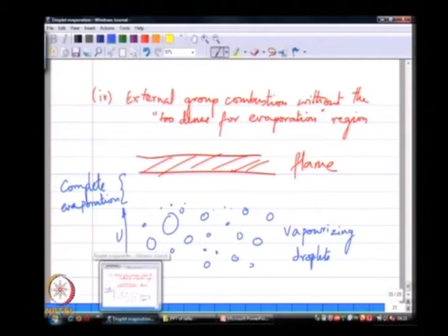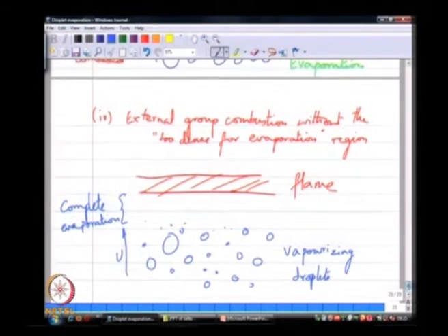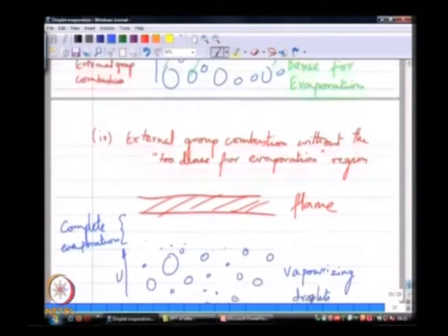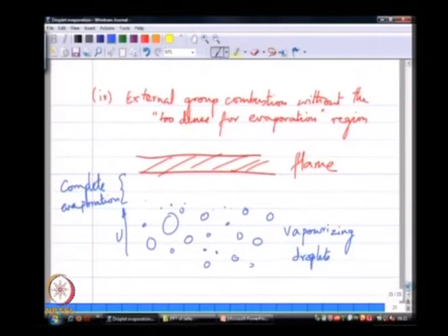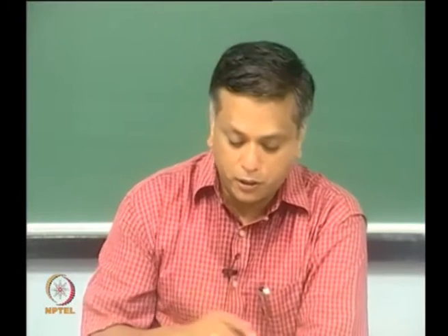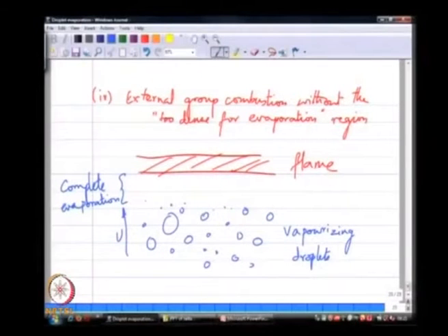This is our fourth mode of combustion. This is also in fact a very desirable regime of operation, primarily because your flame is entirely sustained by a homogeneous mixture of vapor and air. So, you are more likely to eliminate rich and lean spots, or mixture ratio or equivalence ratio fluctuations, the spatial fluctuations in the equivalence ratio.